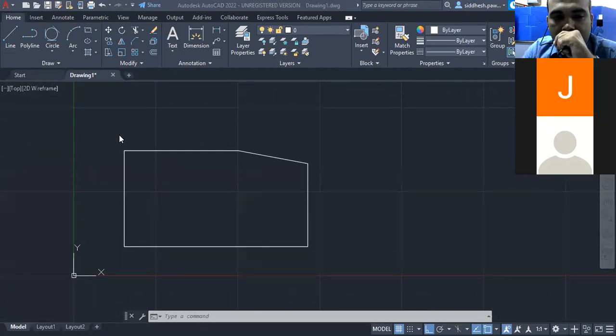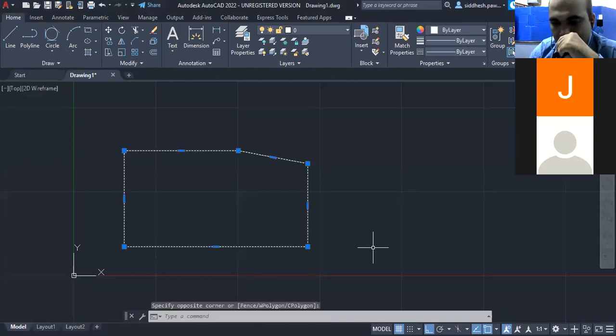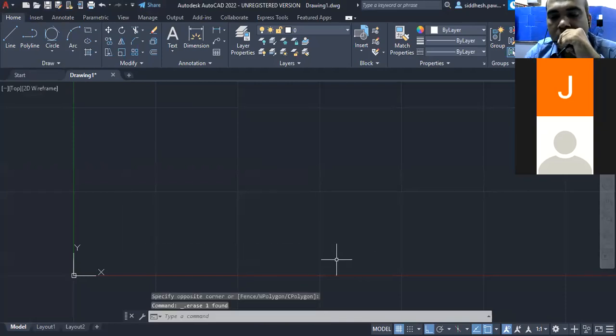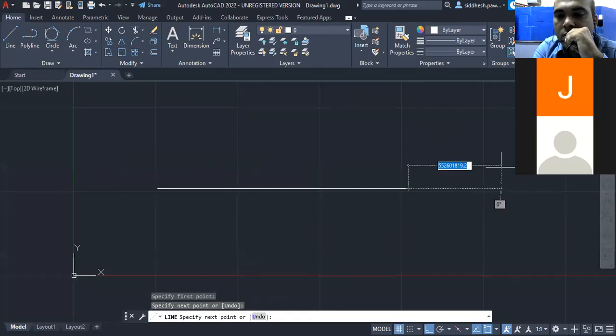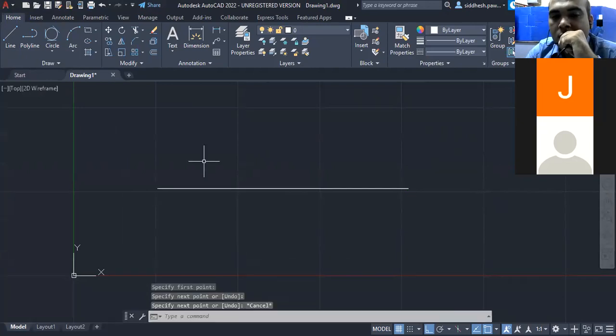Okay. So now left click, drag, delete. So we have deleted. Now what is the next thing we have to do? The next thing is, suppose I want to make an offset. What do we mean by offset? Say I'm making a line here. And now I want a similar line above as well as below. I want to make parallel lines above and below.